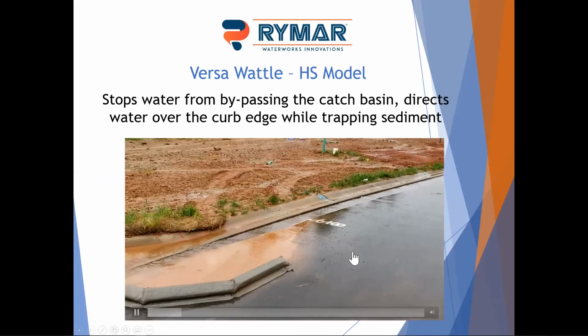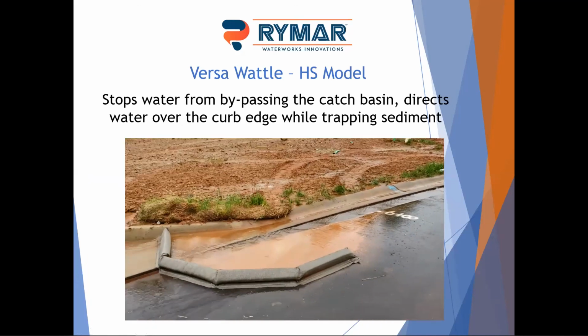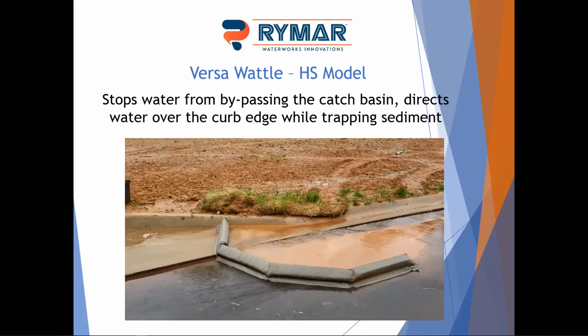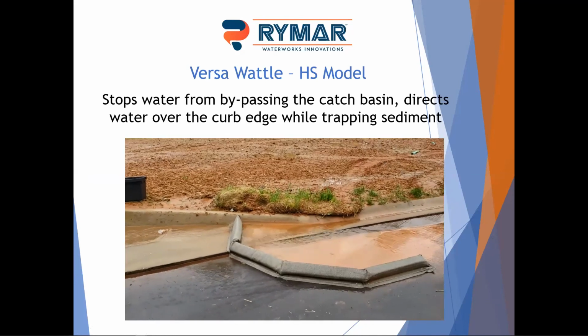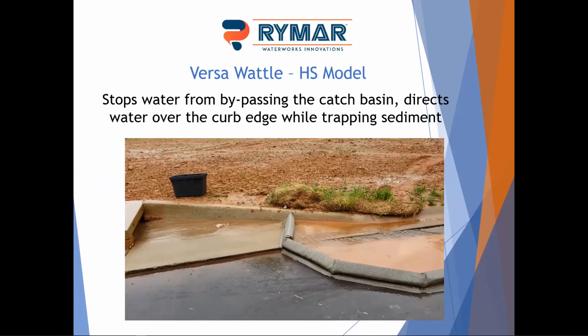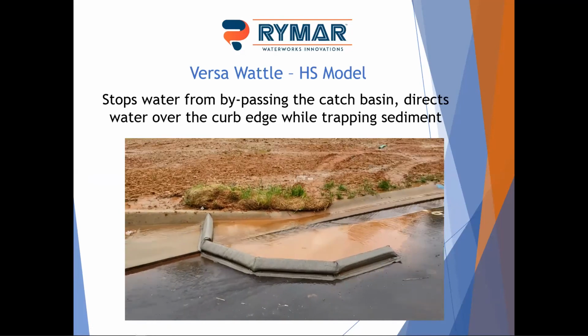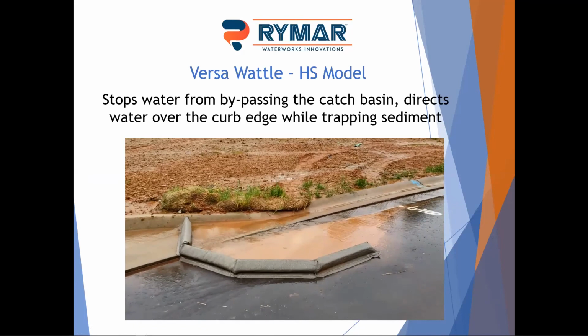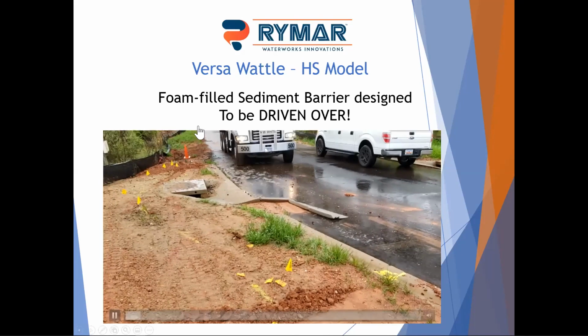Little quick video here to show you how well they work. You can see the water coming down. We're trapping the sediment, and then we're kicking the water over the curb into the catch basin. You can see a good bit of the sediment's being trapped, and the main purpose is to direct that water into the catch basins, so it doesn't bypass while you're doing that trapping. Simple maintenance, just a little shovel to pick them up.